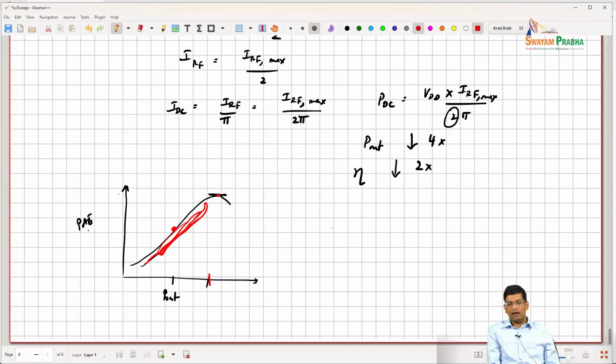And if all you're doing is designing class A, class AB, class B designs, the only thing you can do is make different choices of the load impedance in order to accept some clipping. Maybe you don't back off as much as the PAPR. The PAPR is 11 dB, you back off only 7 dB and you accept the error because overall your EVM is okay, something like that. Or you can come up with architectures that keep this constant somehow. That's basically the idea.